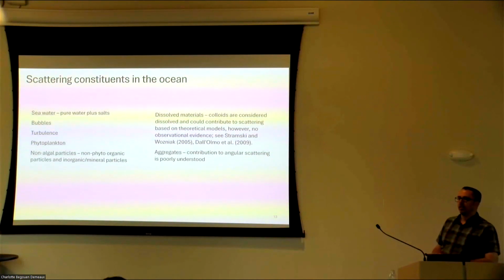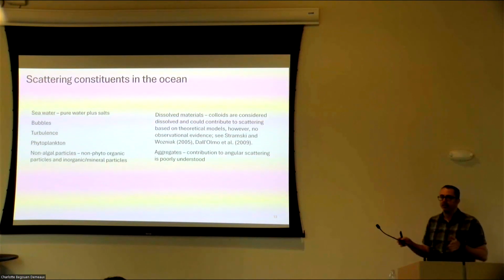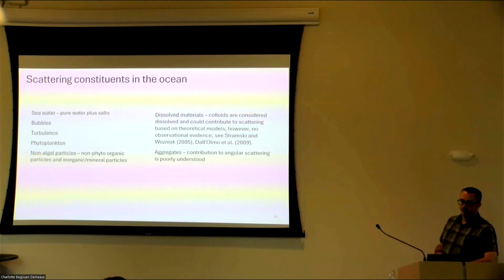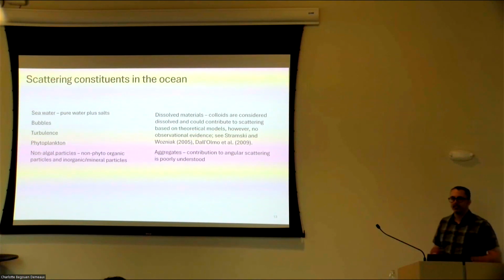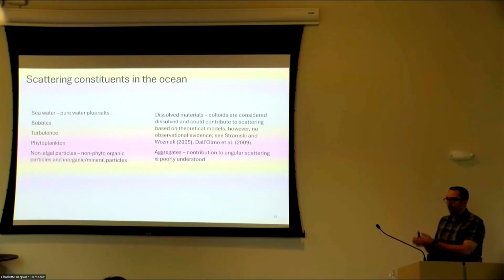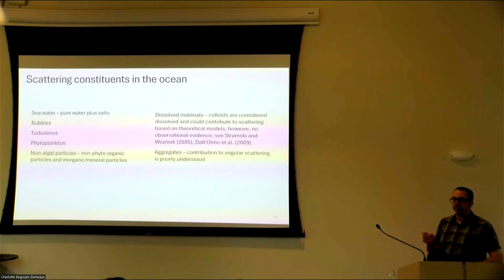Typically, it's going to be a single wavelength, but like Emmanuel said, that has some bandwidth to it. We use a white LED, and we have a special filter very similar to the ACS. It's a linear variable filter that we move through the beam. So we select a 10-ish nanometer bandwidth channel as it's scanning.